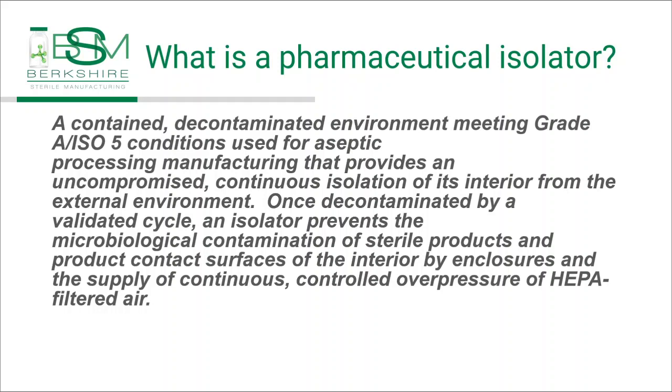It's used for manufacturing. It provides uncompromised continuous isolation of its interior from the external environment, and it can be decontaminated by a validated cycle. It's used primarily in the production of sterile products, and it has a continuous supply of overpressure, HEPA filtered air.